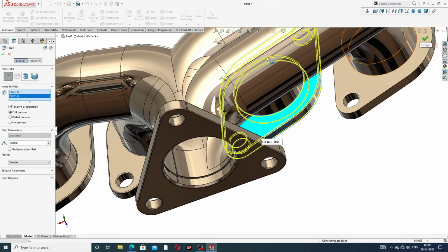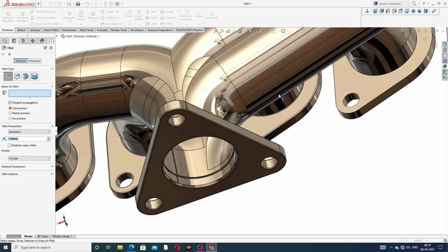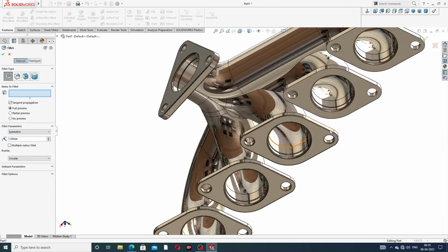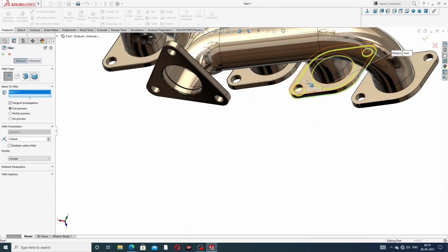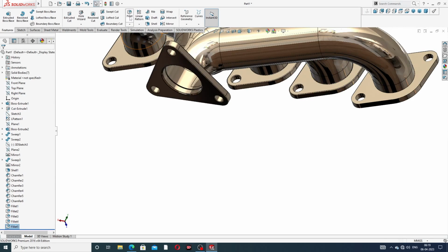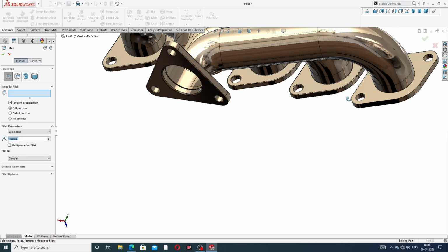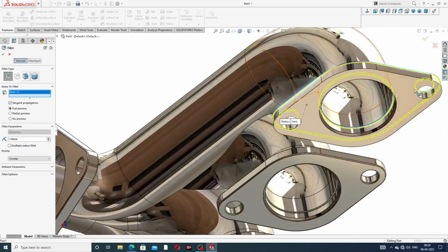Okay, and also use this, and the back side and front side, both faces are selected here 1 by 1, and last is a fillet, use 1 millimeter, select this face and use the back.